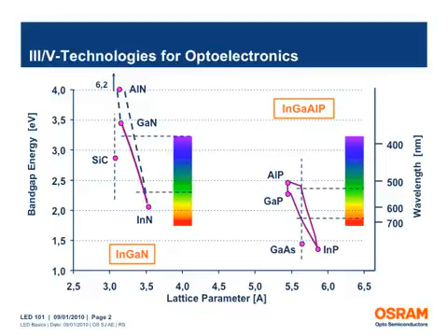The wavelength of light, or its color, is determined by the light's energy. The energy of a light particle emitted by an LED is equivalent to the bandgap of the semiconductor material used for the LED, which is an intrinsic feature of the semiconductor material. Manufacturing an LED with a designated wavelength is all about engineering the semiconductor materials and their bandgaps.